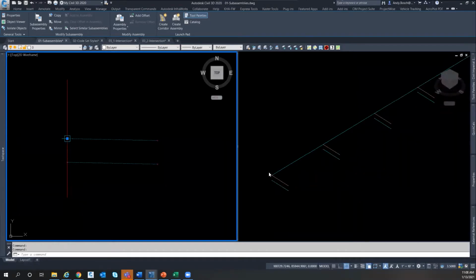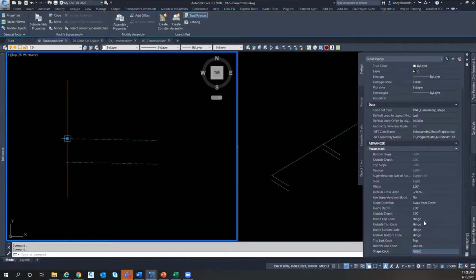Now, along our corridor, every time this assembly gets placed, it's called a frequency. So you can see these frequencies starting to connect here. One of the other cool things is that as we've got these hinge points, we can also do certain things like call out elevations. We can start doing labels for each one of these points. And that gets helpful when you start getting into creating cross sections and doing labeling in that way.